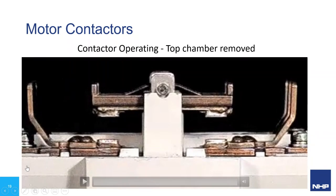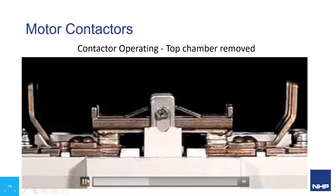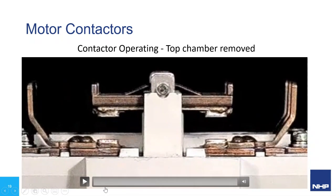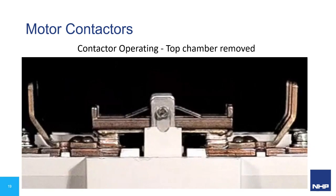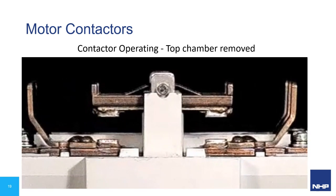The issue we need to fully understand here is that motor contactors have not been tested against the applied characteristics of multiple DOL starts from IE3 and IE4 motor loads of any size, not just the larger styles. So effectively the contactor will be subjected to a higher than designed locked rotor current and a low level short circuit every time it DOL starts a motor. Because of this, the contactor is way beyond its AC3 duty compliance level.